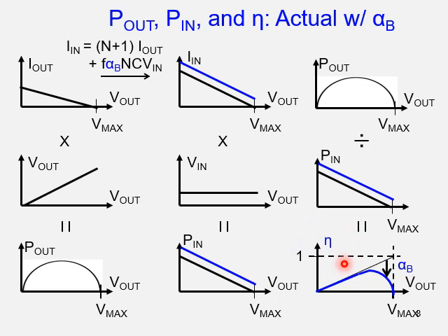So to get eta, you have to consider that increase in P in, especially at this point where the output voltage is high. Then the output power is significantly reduced down to 0. Therefore, at this point eta goes down to 0 rather than going up to 1. So in this result, you should consider there is an optimum point to maximize eta in terms of the output voltage.